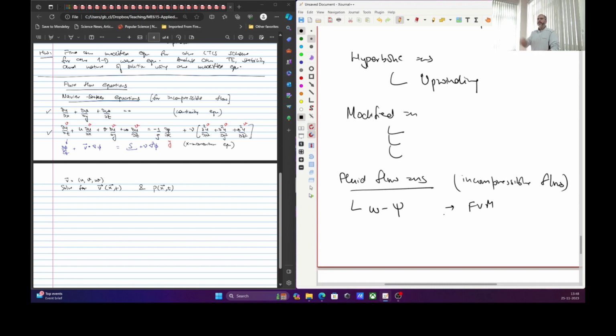But if you consider all of them streamlines, then where do you introduce the idea of u equal to u not on the top boundary? So you see that you have to figure out sort of hacks to implement boundary conditions with these. Because of this problem and others, the other major problem is it only works for 2D, doesn't work for 3D flows. So then we moved on to full 3D solvers.